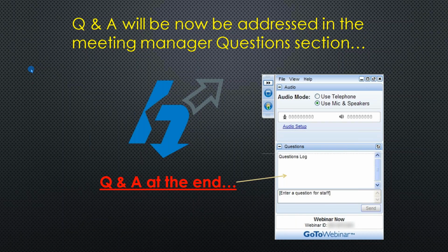The other thing is, once you get the analysis software tweaked to where it's predicting what you're seeing, the whole point of convergence is so that you can run multiple tests, refining the element count. The more elements you get, the more accurate your analysis is. The fewer elements, the less accurate. I could turn these meshes down to a very coarse number, and my stress calculations and deformations will be way off, grossly off, unbelievably off.